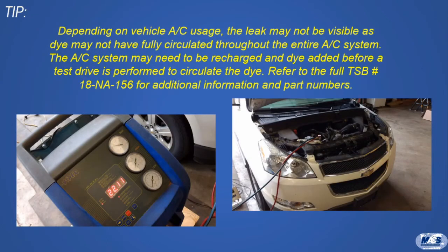And here's a quick tip. Depending on vehicle AC usage, the leak may not be visible as dye may not have fully circulated throughout the entire AC system. The AC system may need to be recharged and dye added before a test drive is performed to circulate the dye. Refer to the full TSB number 18-NA-156 for additional information and part numbers.